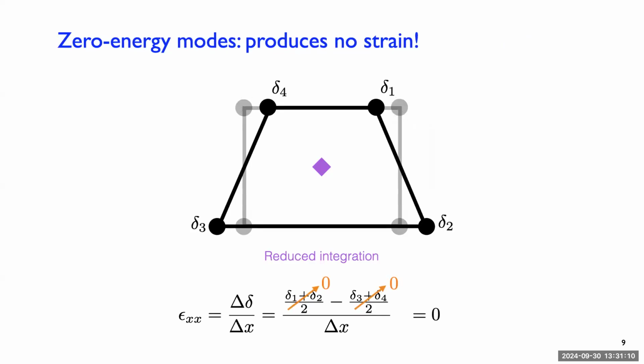now imagine that we artificially deformed our element into this shape, like a trapezoid. And I purposely decided to make D1 equal and opposite that of D2, or delta 2. So that might be -1 and this is +1. That means the average of both of these displacements is 0. So at the center of this edge, the displacement is 0. The average of delta 1 and delta 2 is 0, and similarly, the average of delta 3 and delta 4 is 0. So I purposely chose that displacement field, or that type of deformation.